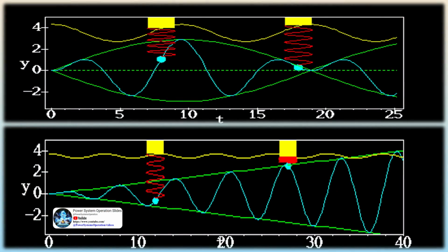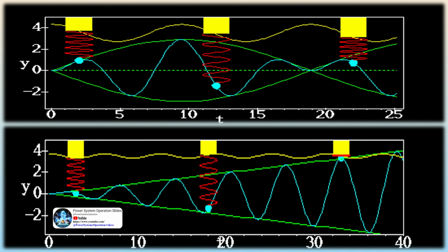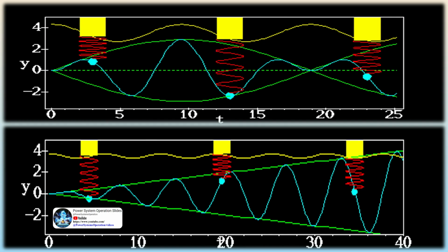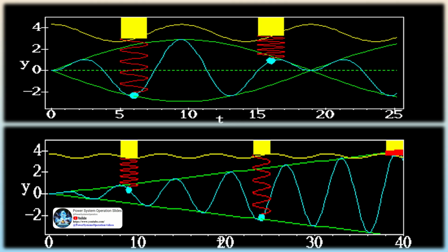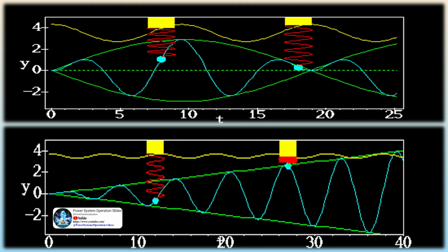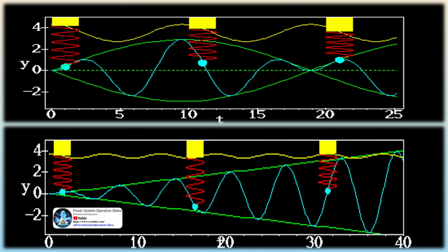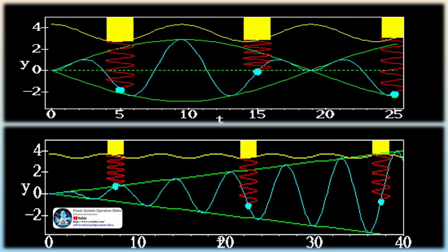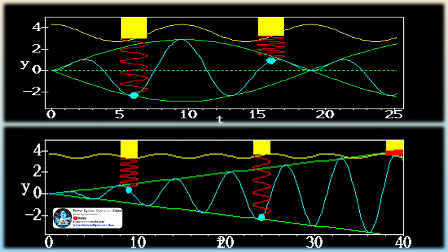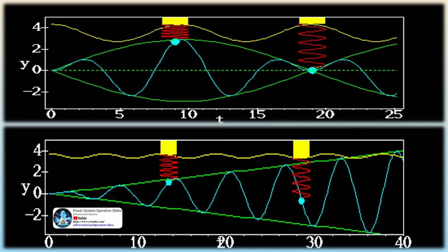When small oscillations occur, the generator's rotational speed increases or decreases due to the frequency fluctuation. However, the turbine control that manages the speed by injecting slightly more or less fuel is not always fast enough to respond to such oscillations. And given that a variety of generators are interconnected in a bulk electric system, each may respond differently, potentially resulting in generators no longer spinning in sync. Thus, it is important to respond to these oscillations quickly.